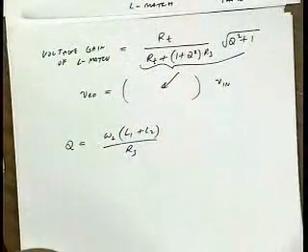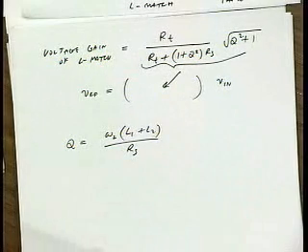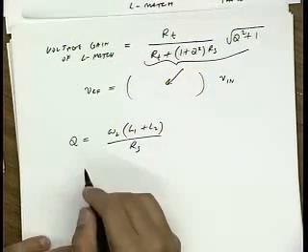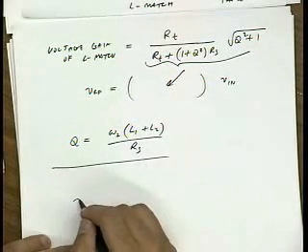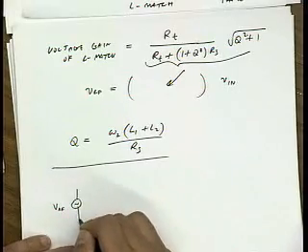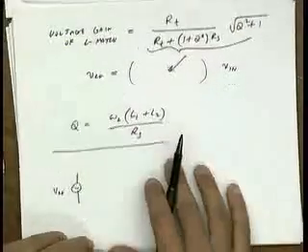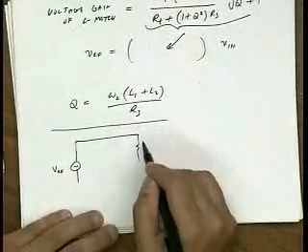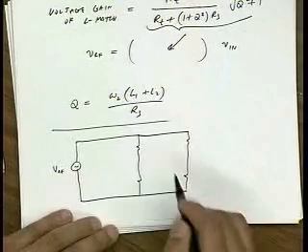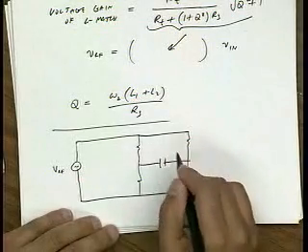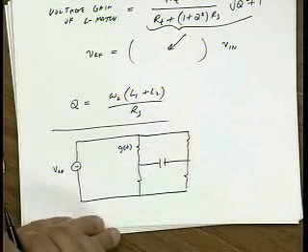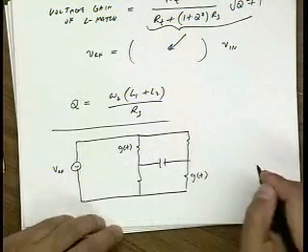Now, to analyze this circuit, it looks like a very simple equivalent circuit would be I have some RF voltage which is generated by this circuit that basically sees the following circuit, where I've replaced each MOS transistor with a time-varying conductance.